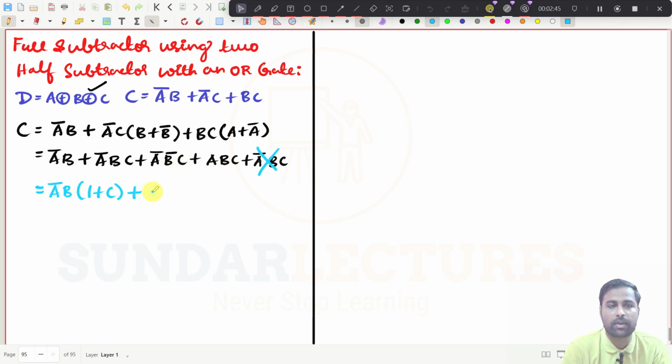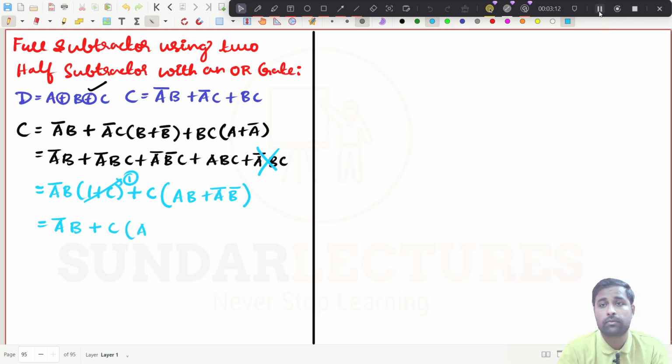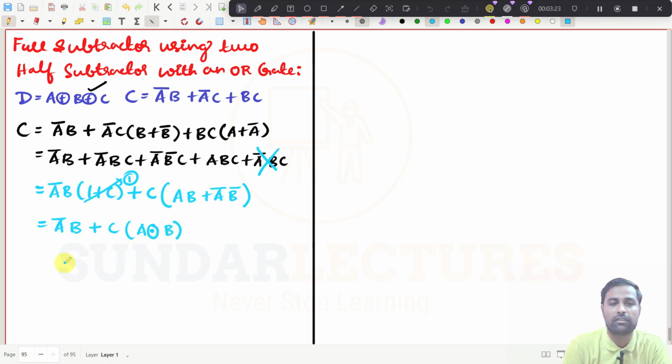It is C, right? So put plus, take C commonly outside now. If you take C commonly outside, what will you have now? It is AB plus A bar B bar, right? Now you will have an expression like this. And what you can do now, you can just write this is A bar B, right? Because this one goes to 1, and this one plus C. See here, what is this one now? Actually this is AB plus A bar B bar. What is this one? This is A XNOR of B. Am I right or wrong?